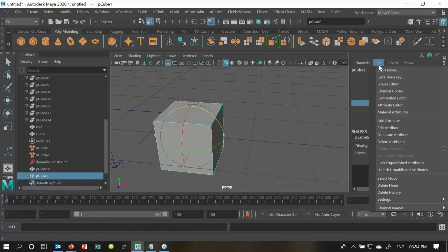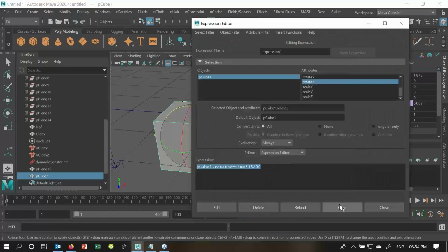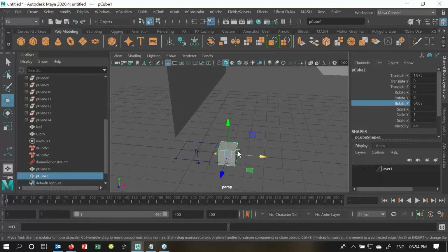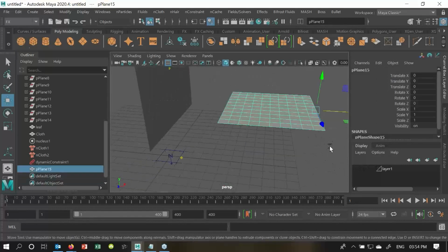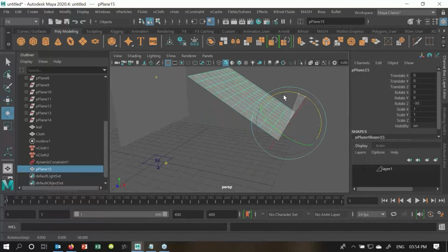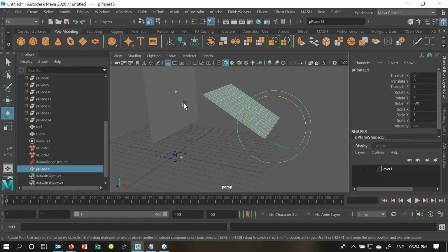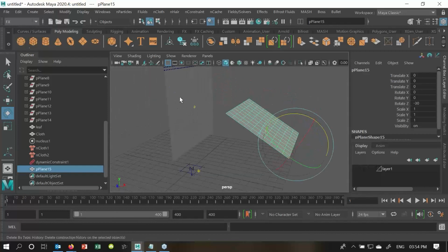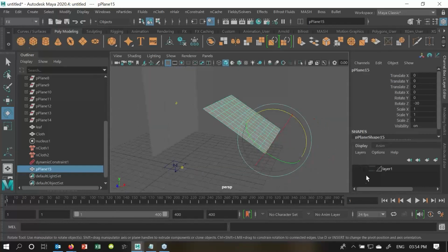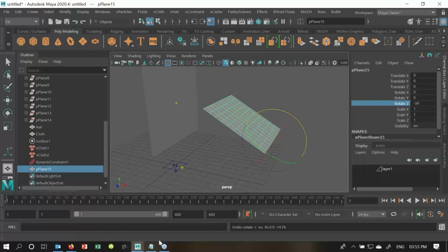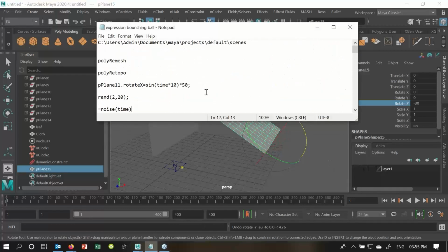Right? So again edit expressions. If I want to apply these same expressions over here, if I make this kind of fan movement, whatever I change, it will apply on this cloth, right? So I'll select this. I have not done the animations till now. Rotate Z. There are some presets which I already wrote over here.